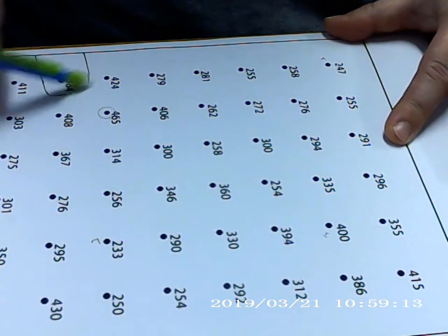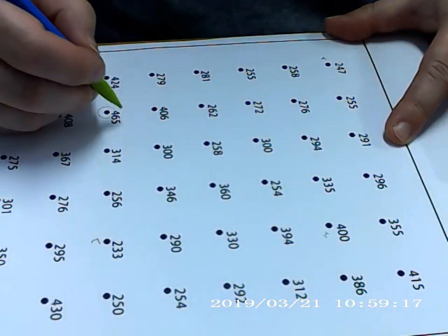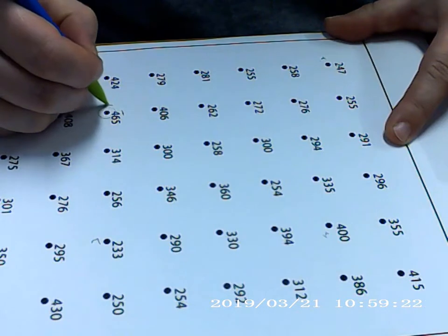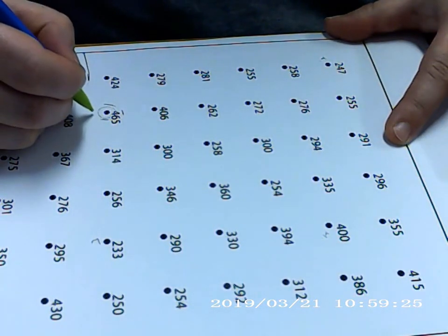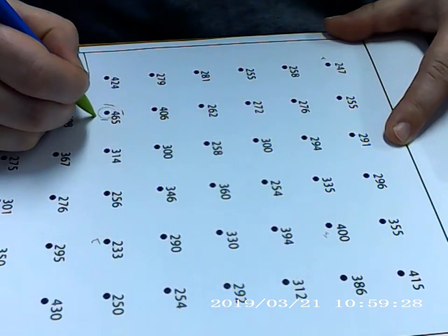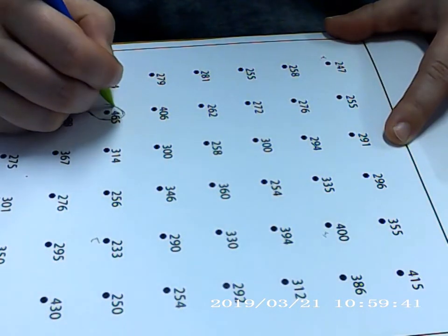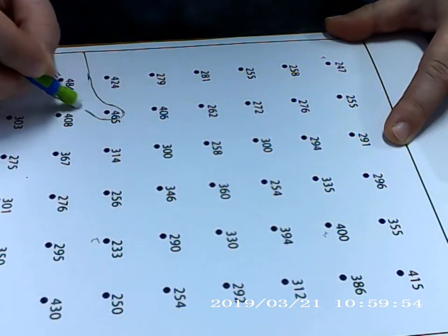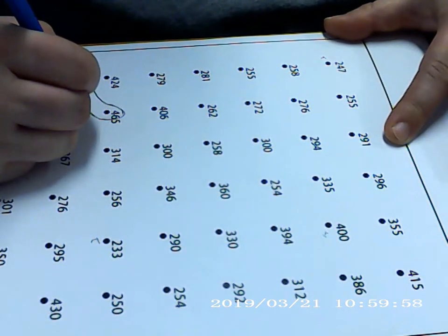This contour should enclose all the values higher than 450, and there is a value of 465 on the wrong side. This is why we contour in pencil, so that we can rub out the wrong bit and include our only other value higher than 450 within our contour of that value. We label our contour. You can put your label beside the contour line, but most professional maps have the labels in a break of the contour.